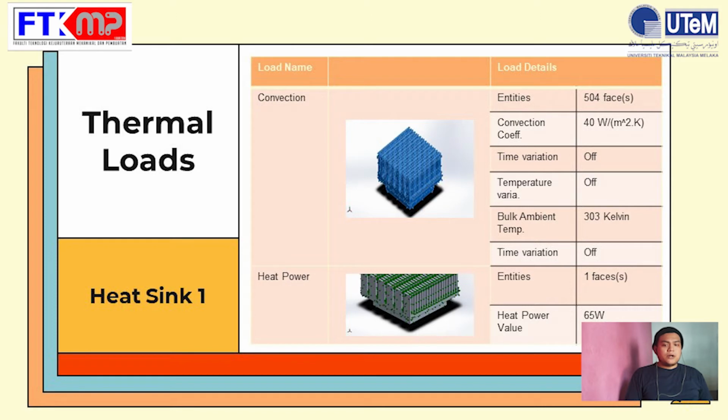For the heat power load, it is applied to only one face of entities, at the base of our drawing, and the heat power value is 65 watt.